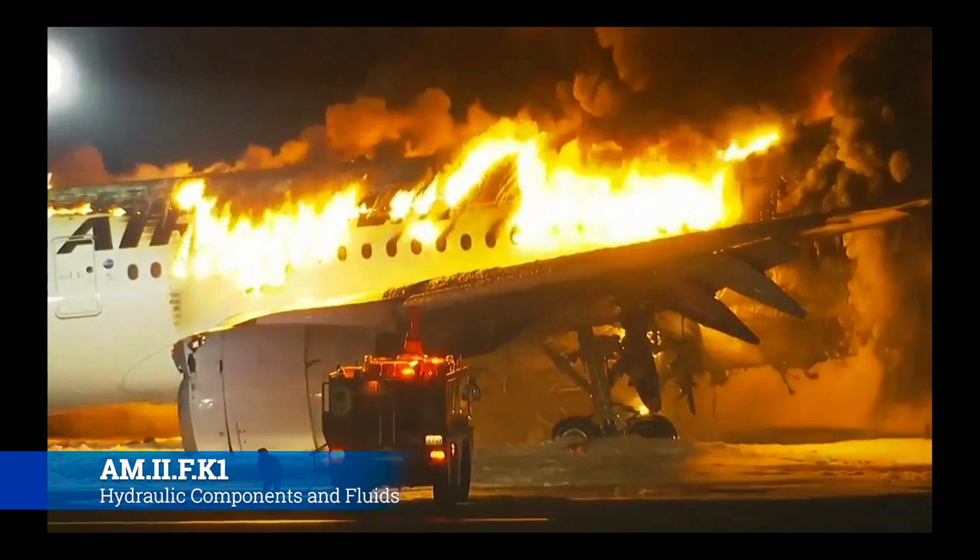Now the thing is that the moment that you get a flash, that heat's going to come up, and you're going to bring that liquid even higher up to the fire point. And the flash point and the fire point usually aren't that far apart, so it's kind of a technicality to separate flash point and fire point, because usually if it's flashing, it's not too far along, it's going to be at the fire point as well. The point being is that there are two separate points in the temperature progression of a fluid. So now let's talk about the different types of hydraulic fluid.